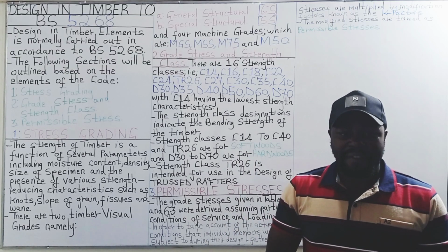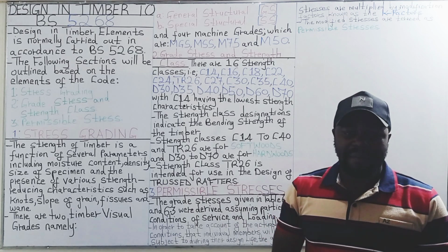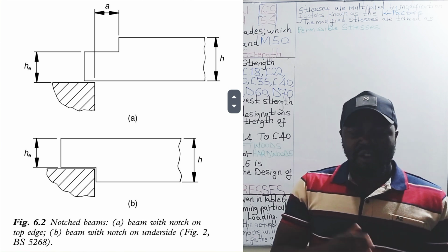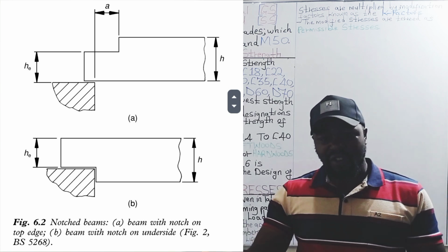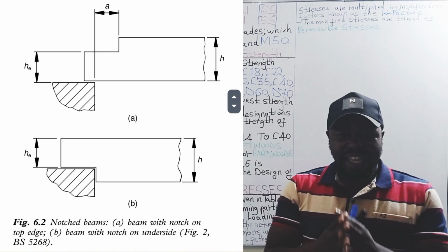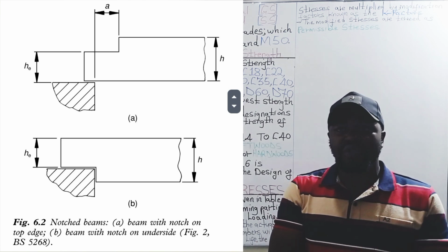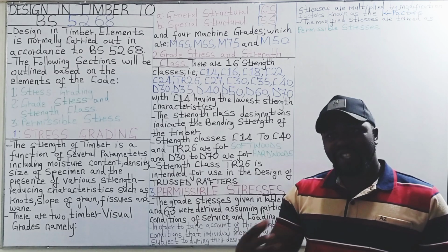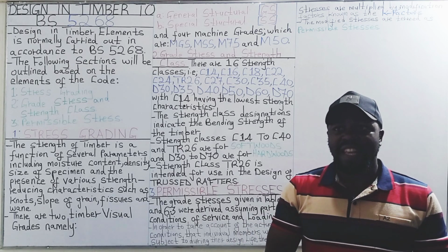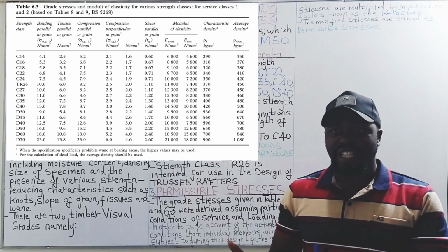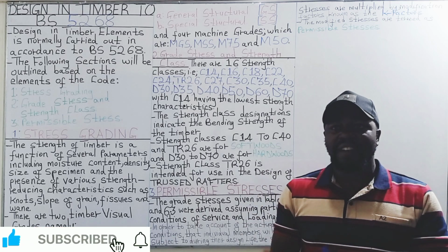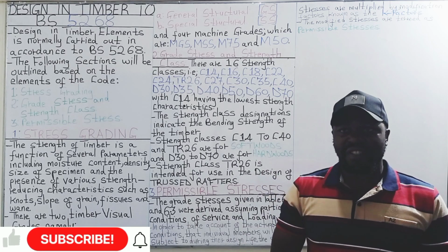Then we go to K5, that is the notched ends factor. And notches at the ends of flexural members will result in high shear concentrations which may cause structural failure, and therefore they must be taken into account during design. And in notched members, the grade shear stresses parallel to the grain, that is table 6.1 and 6.3, are multiplied by a modification factor K5 calculated as follows.